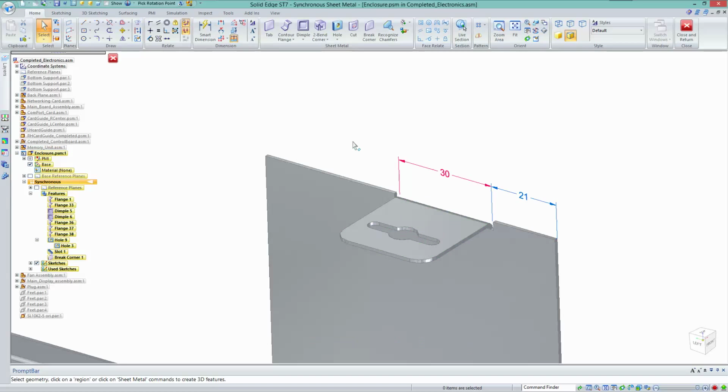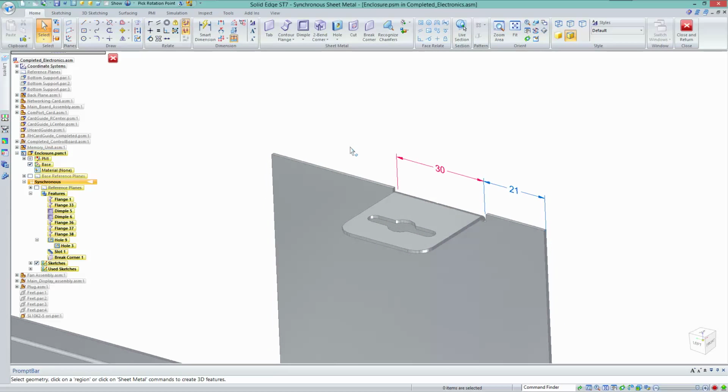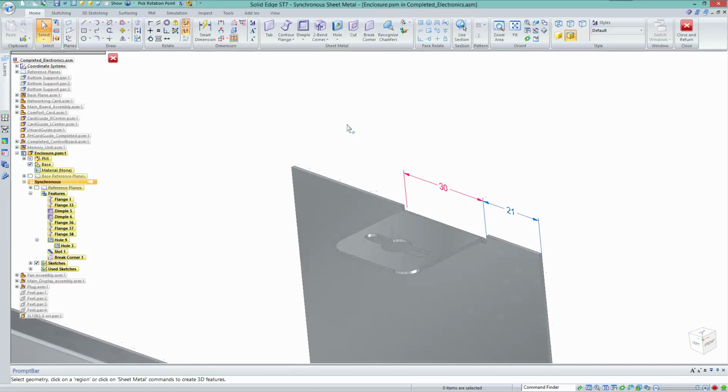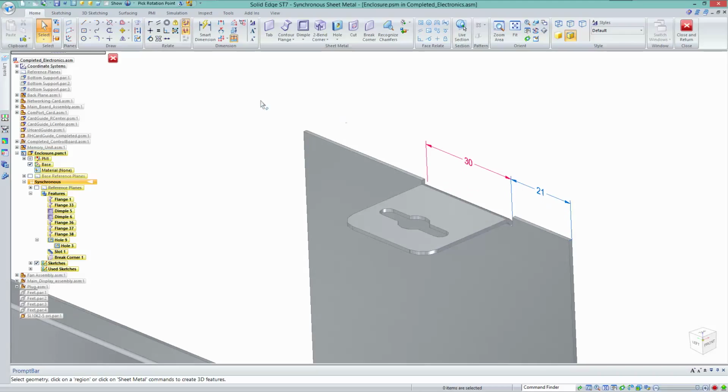Inside the top face of the model. In order to ensure that there is sufficient strength on this, we will add in some deform features. So this is where the Gusset Tool will come in useful. So again, we can select a bend on the model.